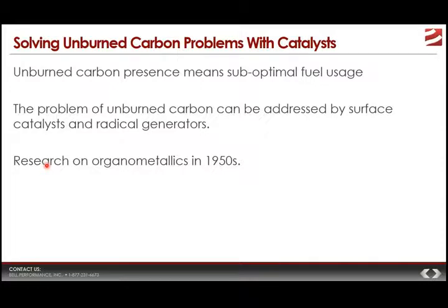Now, what could cause that? Well, it could be that there wasn't enough oxygen. It could be that the fuel wasn't atomized optimally, because droplet size definitely can impact how well something combusts in a given environment. But whatever it is, bottom line, you're not getting everything out of the fuel that you're paying for. And so, in order to address this, organometallic combustion catalysts have been shown to be able to make substantial inroads in solving this kind of problem.